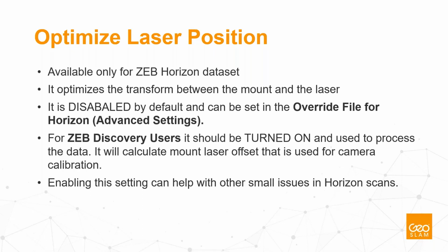It is disabled as default, so if you drag and drop your Horizon data, that is not going to be applied. However, I do recommend to change that setting in advanced settings, where you can preset your parameters before dragging data. So in advanced settings, override file for Horizon, you can turn this on and have that on at all times.